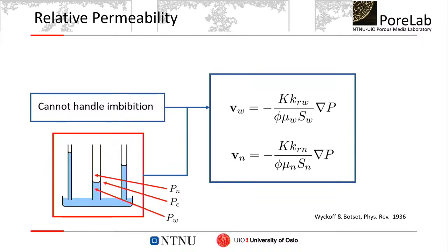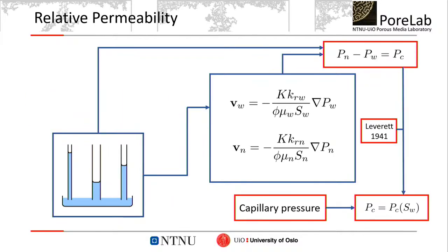and here, the water rises up in the column because there is a capillary pressure that, because of the curvature of the surface, is pulling up. Here's the pressure in the water, and here's the pressure in the air outside, the non-wetting on the outside, and so the pressure here plus the capillary pressure is equal to the one on top, and that's what I've written here.